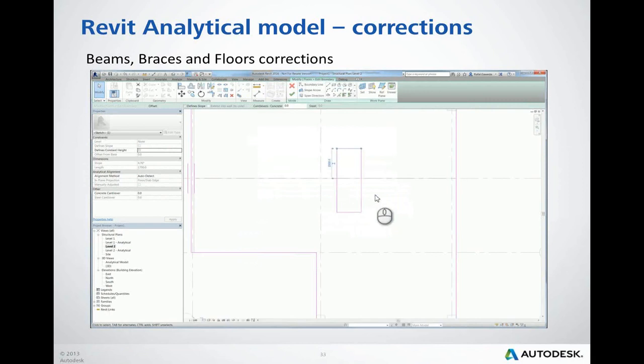But in case of creating openings by shafts, and the same as concerns the wall openings, so they are created by shafts, the shaft geometry should be changed in case of considering this change in the Revit model geometry, the real geometry of the slabs, and also the analytical slab geometry of the opening.